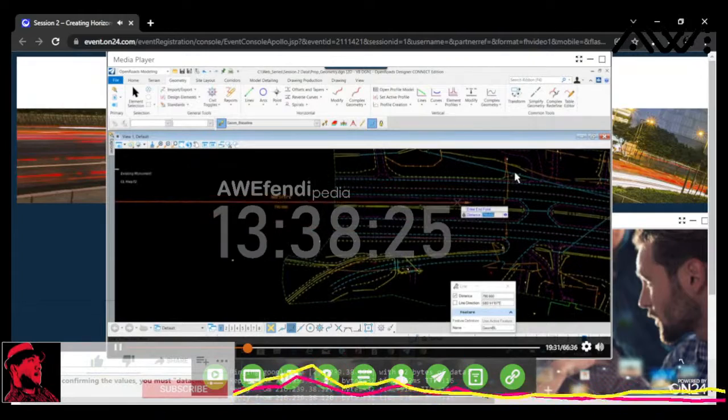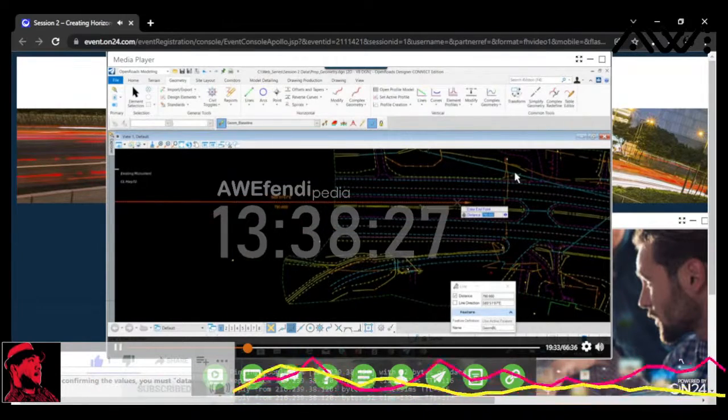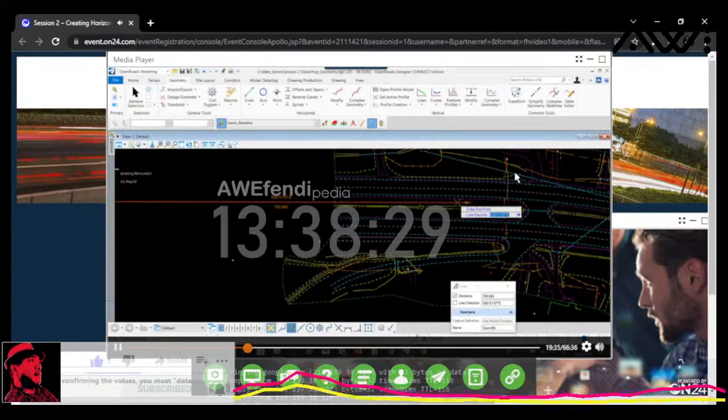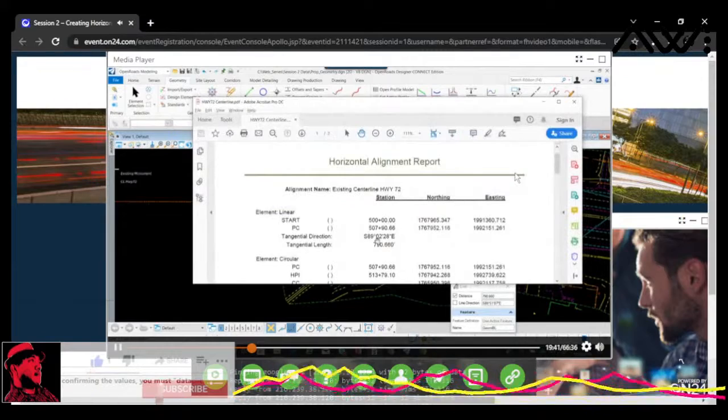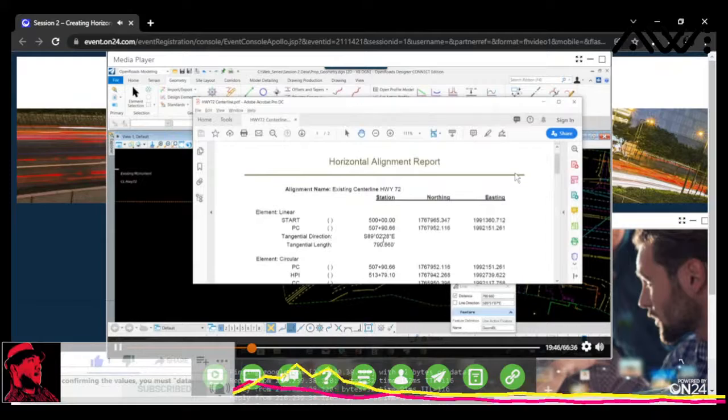Now I want to input the bearing, so I'll click the right arrow, and I get the field to input the bearing for this particular element. So we'll note it's south 89°02'28" east. So I'll show you how to key that in first of all, and then we'll move a little faster.